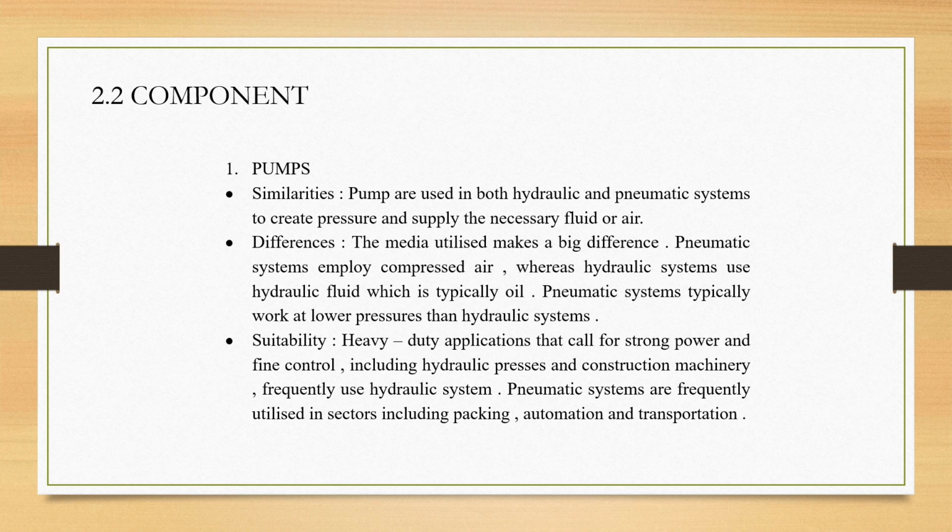The difference is the medium utilized. Pneumatic systems employ compressed air, whereas hydraulic systems use hydraulic fluid, which is typically oil. For suitability, heavy-duty applications that call for strong power and fine control, including hydraulic presses and construction machinery, frequently use hydraulic systems. Pneumatic systems are frequently utilized in sectors including packaging, automation, and transportation.